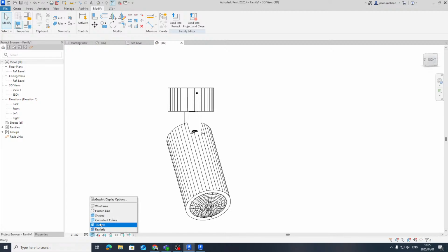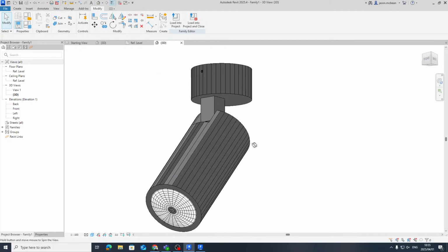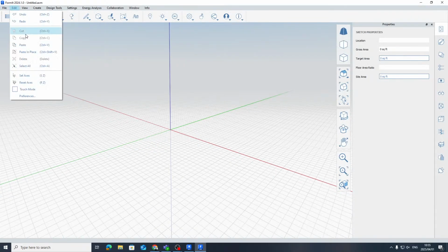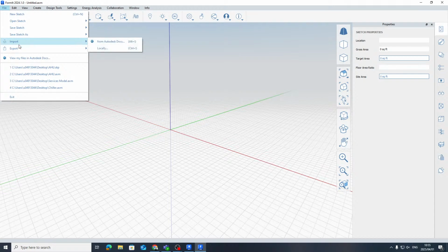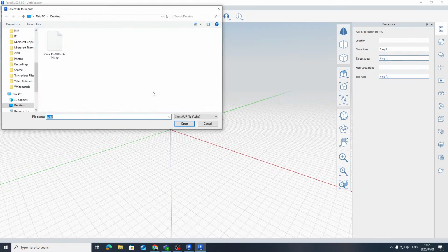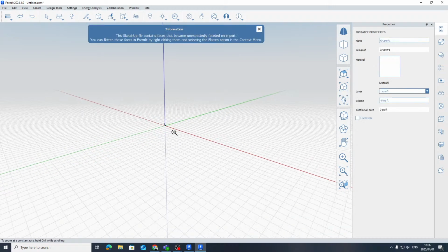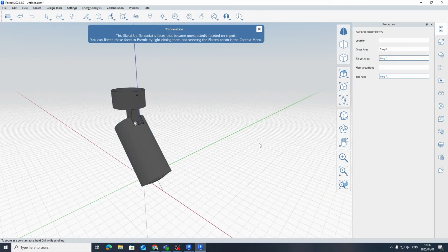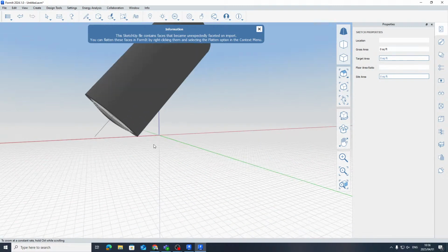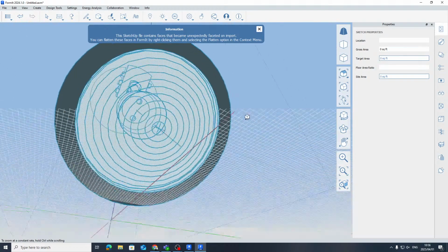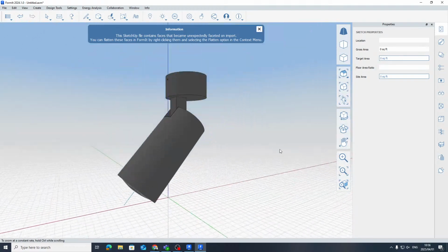Okay, so what we used to do was use Formats. Formats was a great tool that I could quickly convert it into a format that Revit would use better. So this is why we used to use this workflow. So I'm just going to say import, and I'll bring in the same SKP file. I see the scale is quite small, but you see that the model comes in nice and clean. So the glass, everything reads way better. So this model is way cleaner.